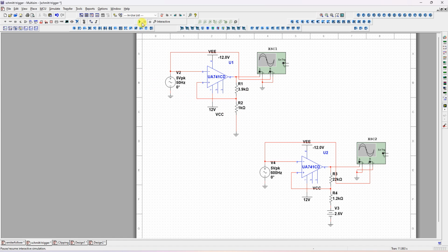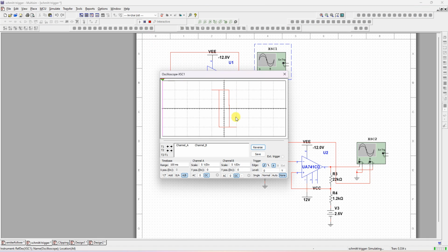So now we'll run this, double click on this, you can check. UTP is plus 2, LTP is minus 2. And if this is AB, it means hysteresis curve. If you give y slash t, you can see input is a sinusoidal waveform. Whenever input crosses plus 2 and minus 2 volts, I'll click single.